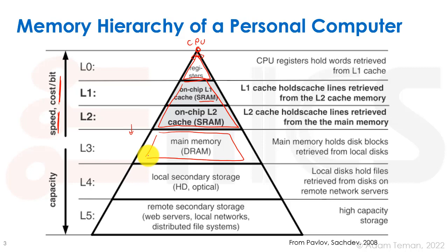But we're able to use a special process to make a memory bit cell that has 1 transistor and 1 big capacitor, and it's much slower because we have to go off chip, and the way it's made is much slower than SRAM. But since we have only one transistor per bit, it becomes much cheaper than SRAM. We can get those higher densities to get DIMMs with several gigabytes of memory on one type of chip.